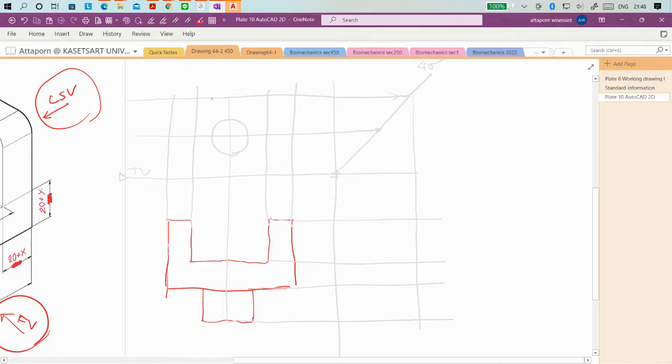After that you can project to the front view, where it will be a dashed line, and you can project this to the top view to make the cylinder under this, shown by a dashed line like this.